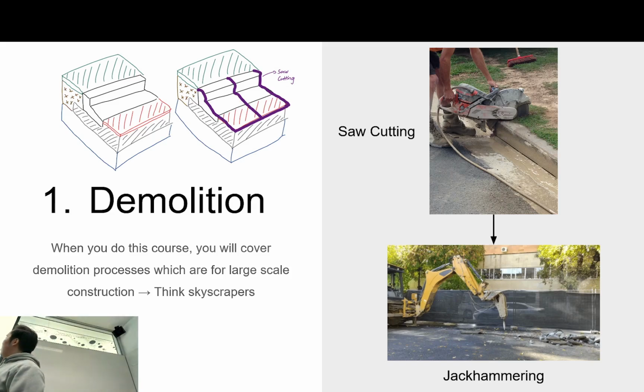So use a jackhammer, break up all the pieces, and they'll switch the tip into a bucket attachment, and they'll scoop all of that rubbish out, right? So the rubbish that they're actually scooping out is going to be the concrete itself, yes, but it's also going to be the topsoil behind it and the grass, as well as that road-base material, okay?